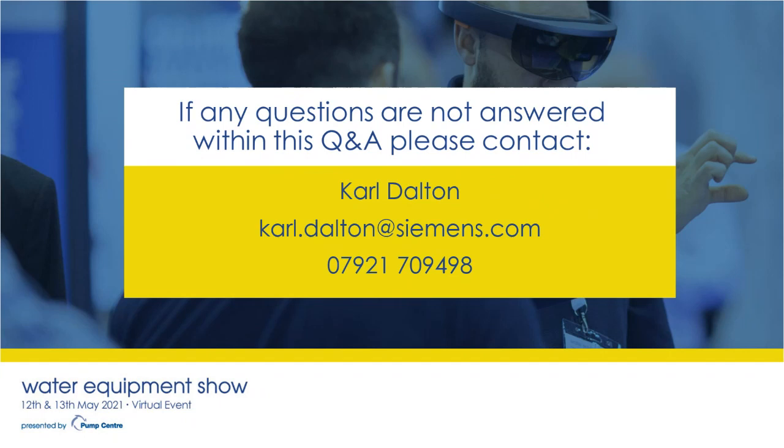So for example, as the wet well pumps down, it's looking at the efficiency of the pump as it pumps down, but maybe the wet well fills back up again, for example, because you've got a failing non-return valve, which in some instances can be missed because those data sources aren't necessarily always collated in, like I said, this single source of truth.